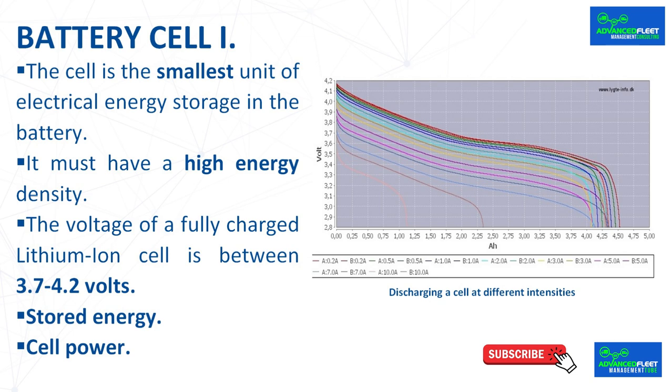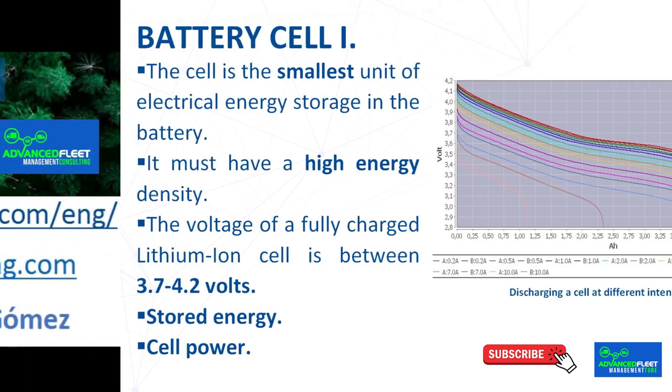In fact, the most strained version is actually the 40 kilowatt hours one, since when we squeeze the 175 kilowatts from its motor, the pack works with current peaks of 4.37 C. However, most of the time when moving without accelerating, the car does not need more than 20 or 25 kilowatts of power, so the battery will usually work at 0.25 C or less.